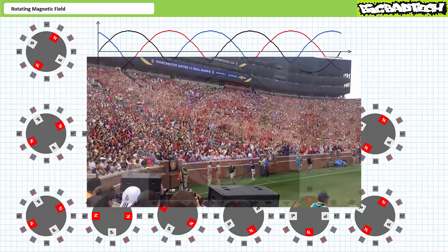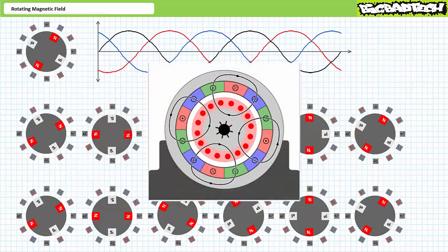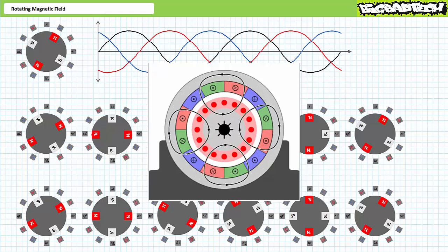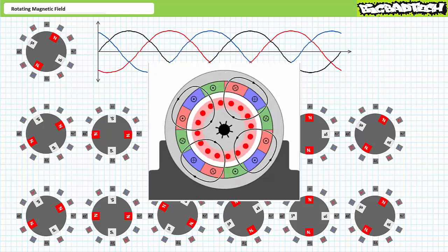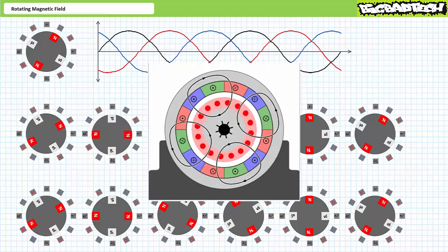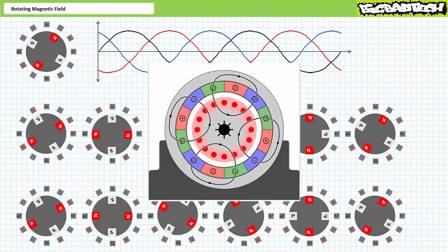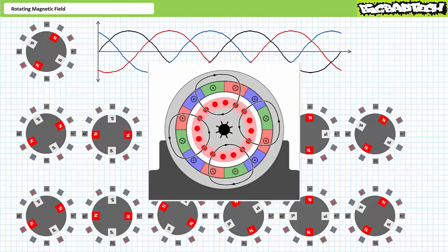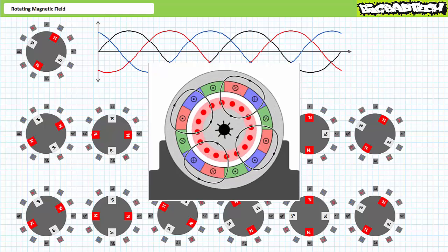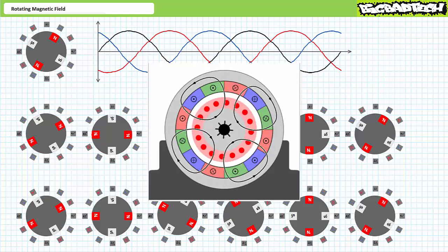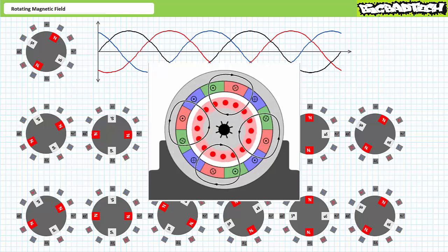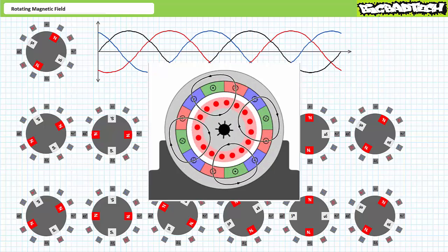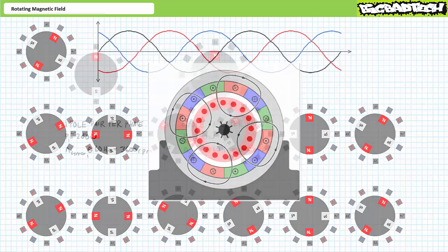Here's a clip from the Wikipedia entry about 3-phase AC motors that I never get tired of watching. The rotating magnetic field, because of the contributions of 3 120-degree offset waveforms and physically overlapped windings, actually appears with a relatively constant intensity, smoothly revolving around the stator. The observant among you may notice something interesting about the relationship of the stator and the rotor speed. I'll return to this clip at the end of this lecture to explain this phenomenon.